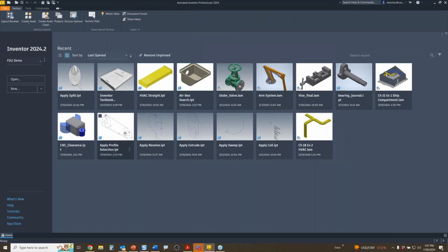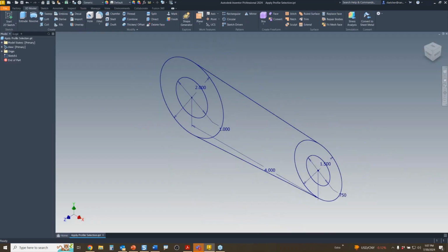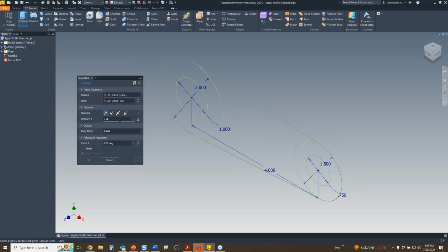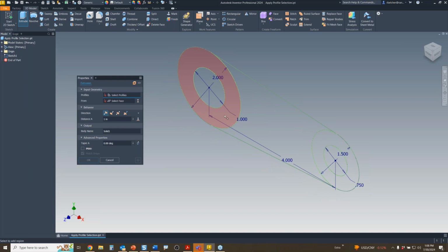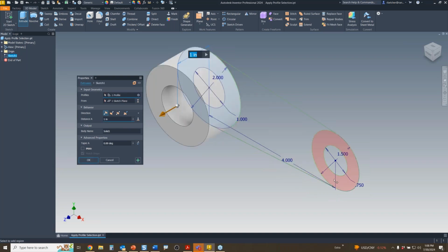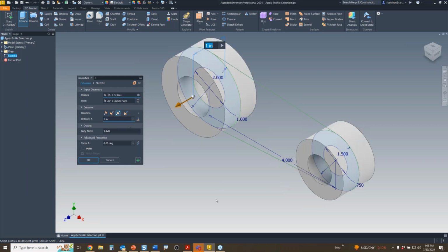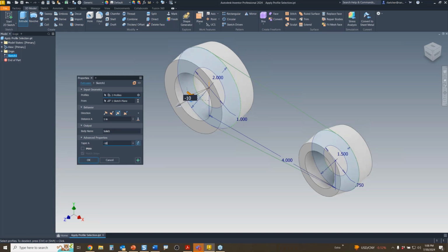So I'm going to open up this example right here. I've got the sketch done already, and I want to do some extrusion work. Let's start an extrusion. I'll press E for extrude. Hopefully you've got the hotkeys down and you can use those things. I've got a boundary selection, so I can select those two areas right there. We'll set it up for mid-plane. Let's do something fancy. Let's taper. All right, so I've got a taper here. I'm going to do -10 degrees.